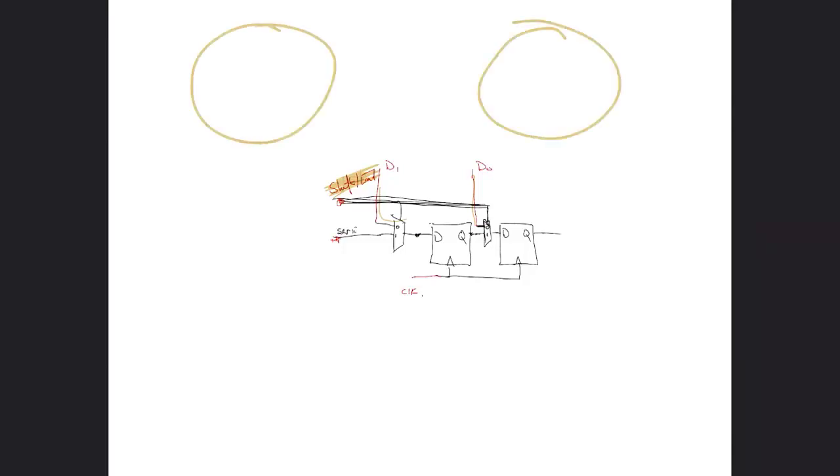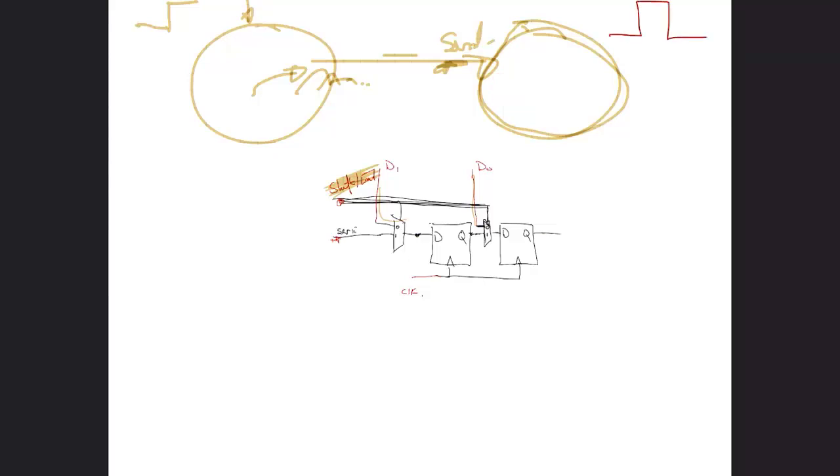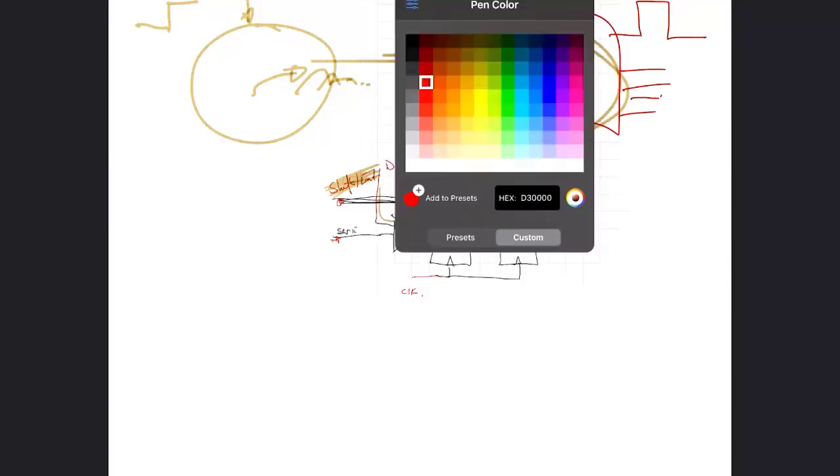So there's the transmitter. There's the receiver. There's one line in between. You can see my screen, yes? Yes. Start TX tells this thing, push all the bits through. So it goes from low to high, and then this thing starts to shift the bits onto the line. This here looks at serial. Serial is this line's name here. And it says, okay, I'm receiving stuff. As soon as it's 0, it goes into receiving mode. It then shifts in until it's received the stop bit. And then as soon as it's received the stop bit, it makes data ready high for one sample, so that the receiving microcontroller, or whatever is using this receiver, knows that the data is ready, it's been received. Okay, now go ahead with your question.